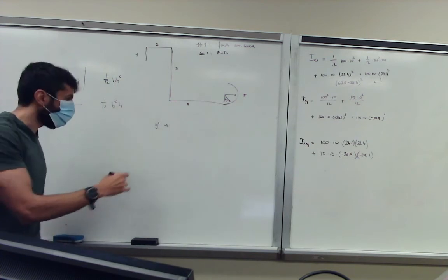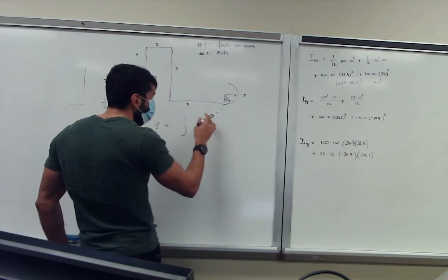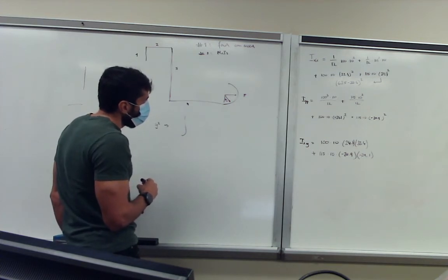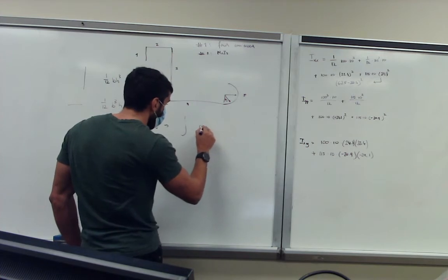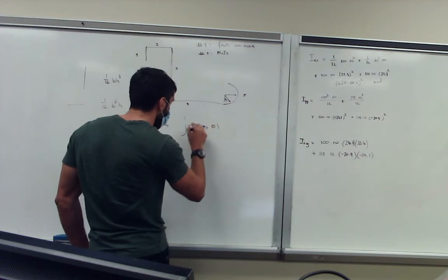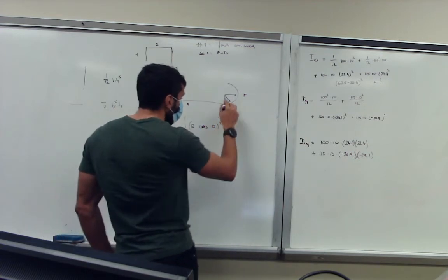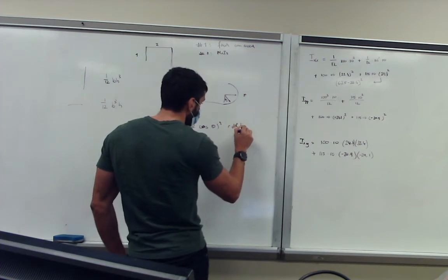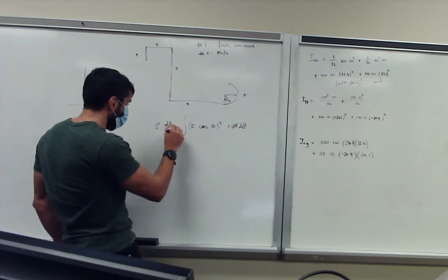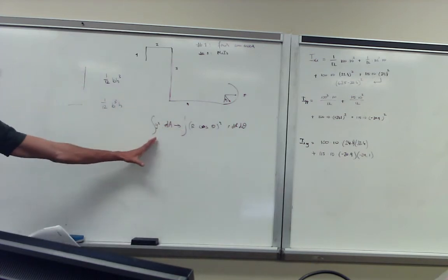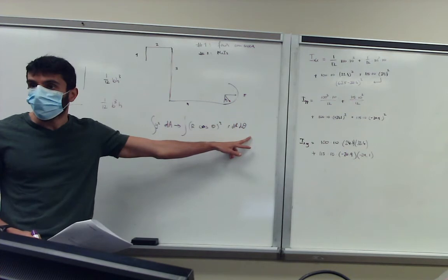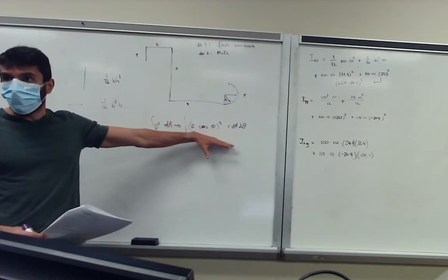theta, and you derive your equation. You say the y distance is equal to r cosine theta, so r cosine theta squared, right? And then you do r dr d theta. That's your coordinate transformation. Your integral basically transforms from y squared dA to r cosine theta squared r dr d theta. But this is already done in literature for you.